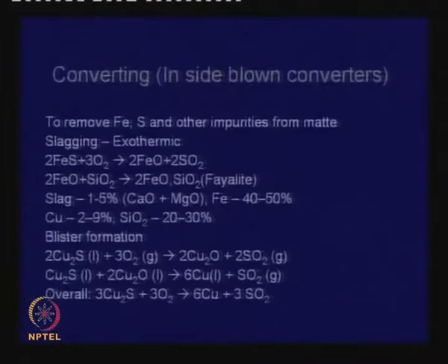And yet, if we allow too much oxidation of iron, then slagging would be difficult. So, the idea would be to take it only to FeO stage, which can be removed. So, we ensure that Fe does not go into the higher oxides, and that is why we leave some FeS behind, and we get a matte which goes subsequently for smelting operation and converting.